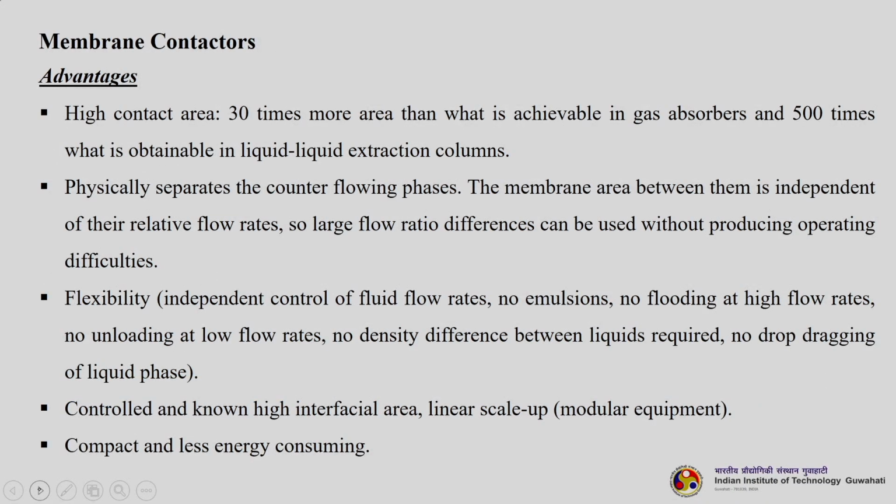So, the advantages are a high contact area, 30 times more area than what is achievable in gas absorbers, and 500 times what is obtainable in liquid extraction columns. It physically separates the counter flowing phases. The membrane area between them is independent of their relative flow areas. So, large flow ratio differences can be used without producing operating difficulties.